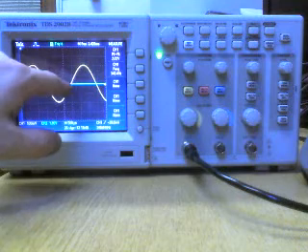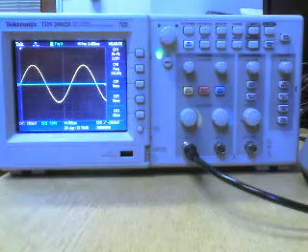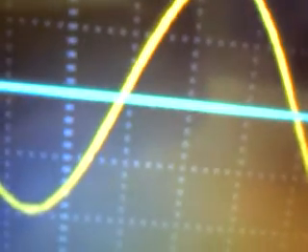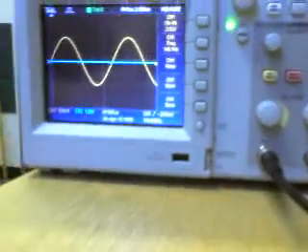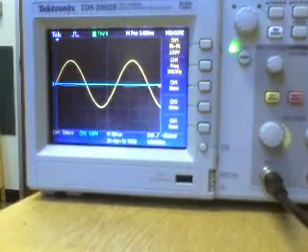If we take a look, you can actually see that's because when I manually measured it, I missed out a little division, a little subdivision. If I move this in closer, okay, you can actually see it doesn't cross the centre of these two divisions. It's just before, so my manual measurement was slightly off. So this one's more than likely a more accurate measurement than I manually measured, which is why I said earlier that always try and keep the largest waveforms possible on the screen.